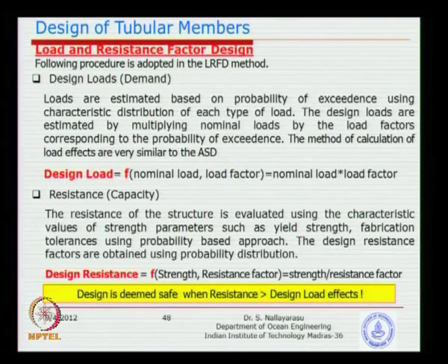Let us move on to the load and resistance factor design, or so called limit state design. In this method we do exactly the same procedure, except that the loads are evaluated scientifically. We do a probability distribution of each of the loads. For example, you have dead loads, live loads, environmental loads, and then seismic loads. So, 4 categories of loads.